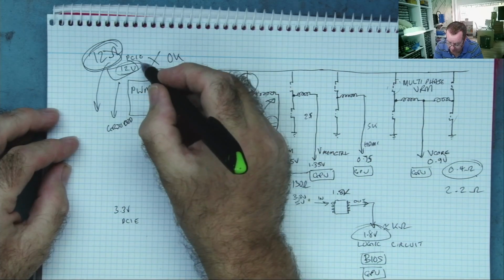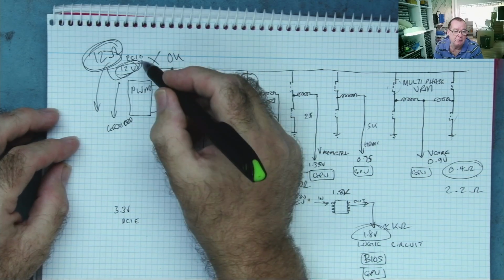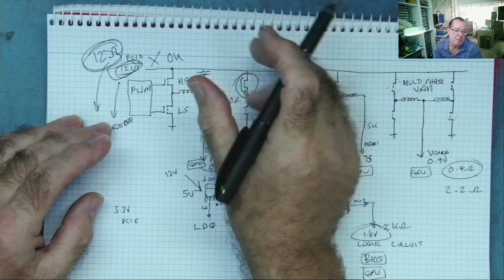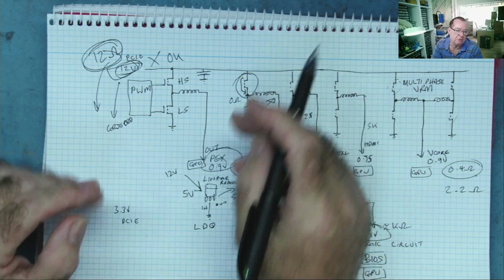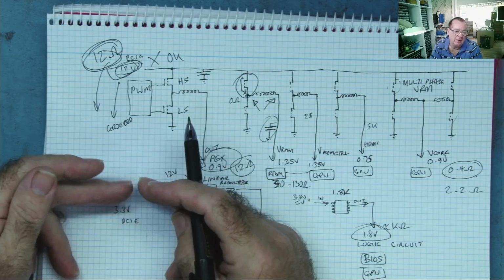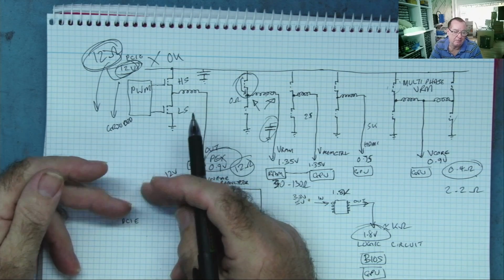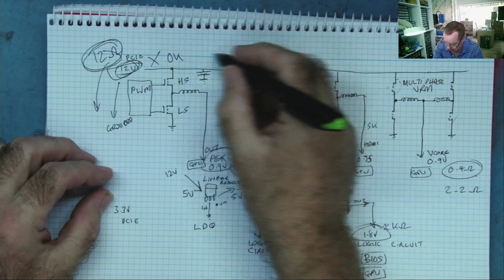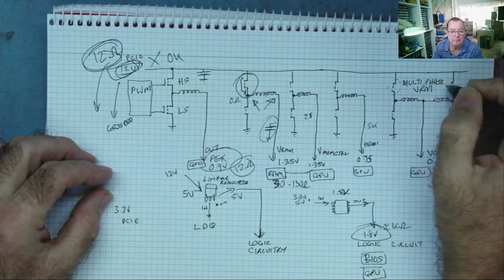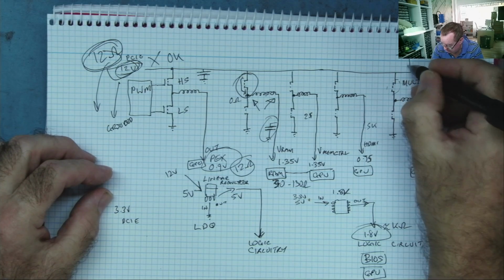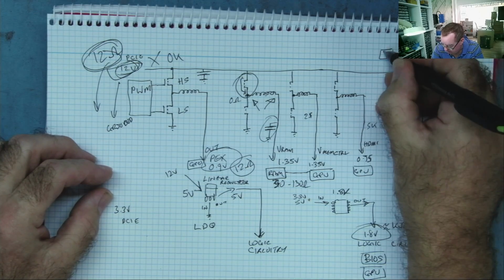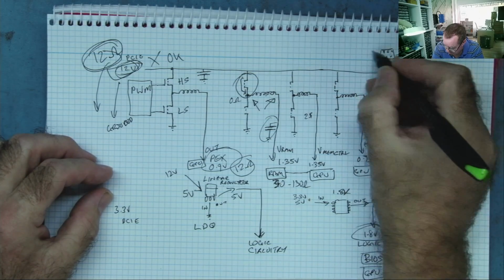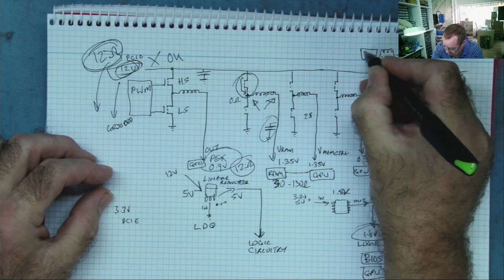And by the way, when you check the 12 volts, always check on the 6 or 8 way connectors on the top edge of the graphics card, and also check on the fingers of the PCI connector, because you can quite often find that, for example, the VCore is coming from the connectors on the graphics card, 6, 8 pin, these sort of things you find on the top of the graphics card.